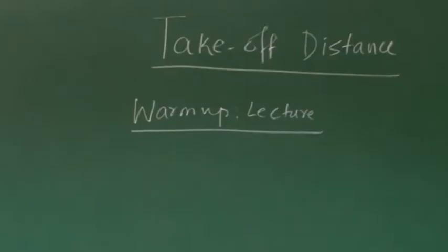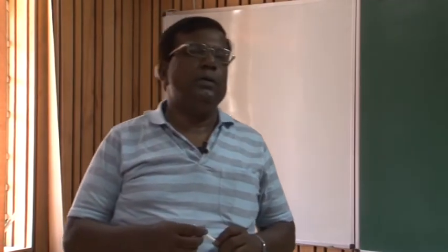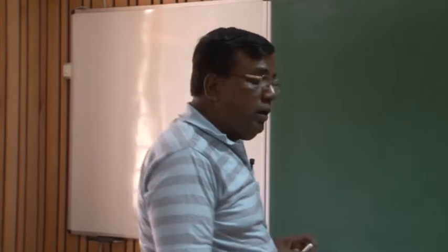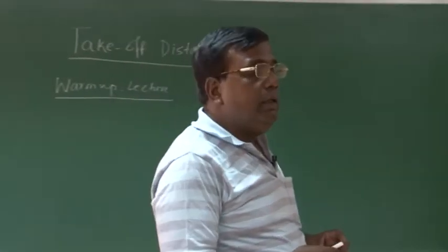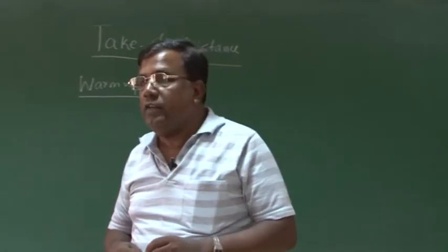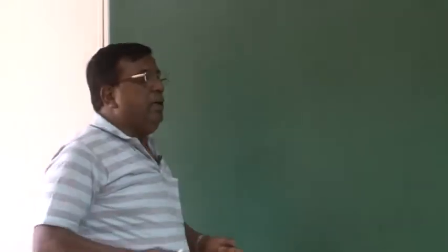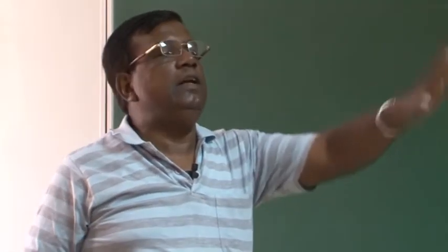Welcome friends. As we have seen, we are warming up ourselves to be ready to understand how to estimate takeoff distance. And you by now also know how important it is that we design an airplane and try to ensure that the takeoff distance is as low as possible. What do we mean by takeoff distance? Loosely, I want that length of airstrip where I can go from v equal to 0 to v equal to a certain speed, and I should be able to take off, in a loose sense.